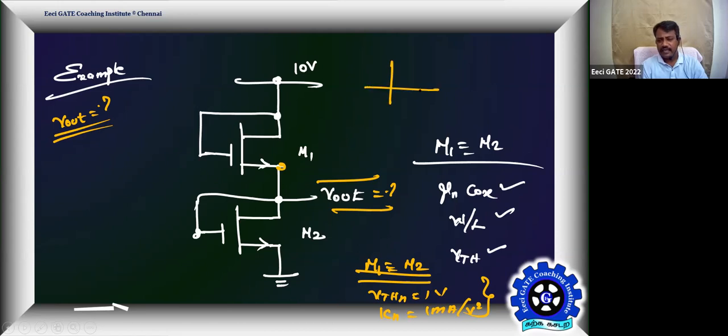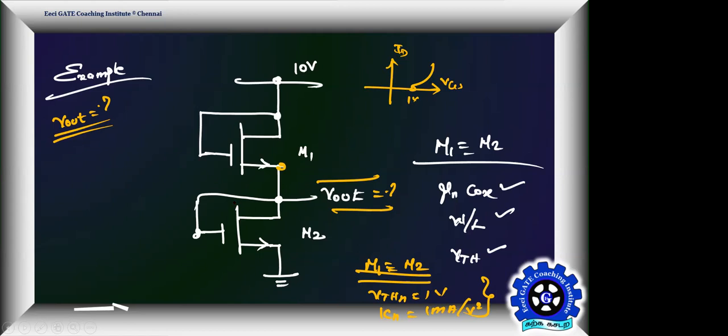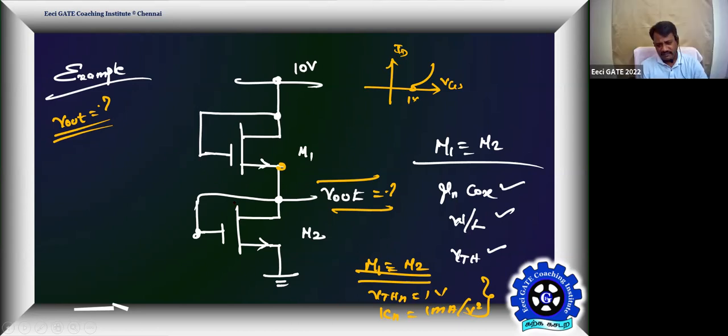That's a characteristic of the NMOS transistors. But I said a clue. If the gate and drain of a MOS transistor are connected, then the device is always in saturation. One piece of information we know. But the problem is, what is the potential V out?